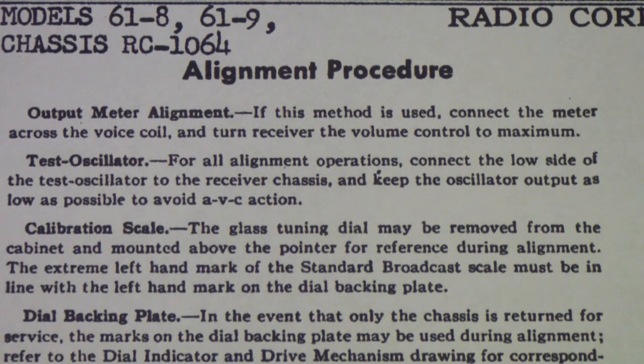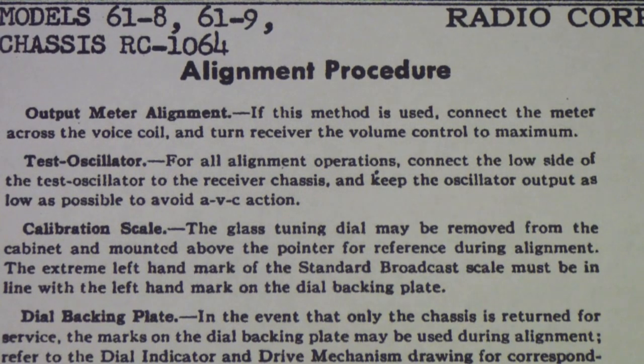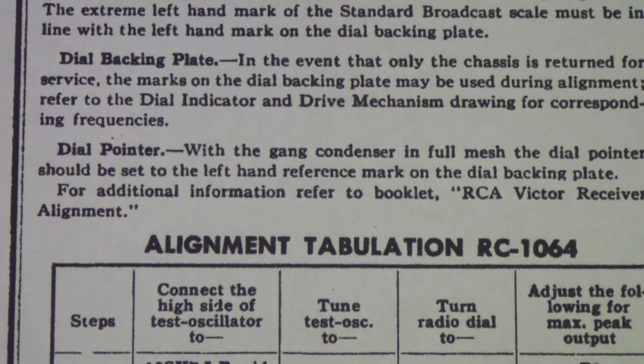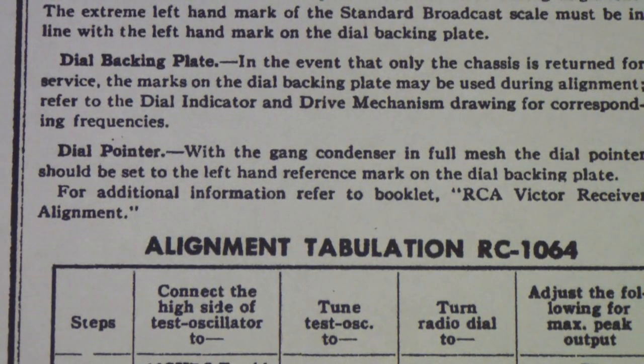The first thing you need to do is make sure that you have the dial pointer hooked to the right place on the dial cord, so that when the dial pointer is all the way at one end of the scale, in other words, that the capacitor is fully unmeshed. Notice how the rotor and the stator are fully unmeshed, all the way at one end of the rotation.